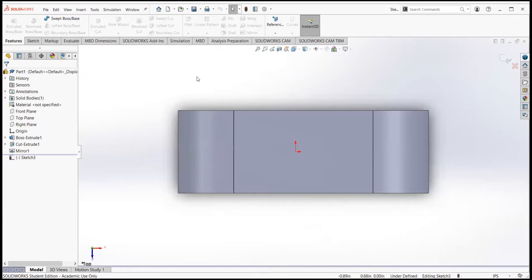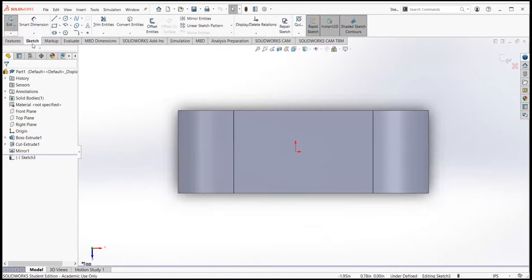We will use a new option which you cannot find on the sketch. It's very similar to the mirror entities, but with this option, as you are drawing, it will continue mirroring your entities. First, we want to define the center line in both axes for your top view.